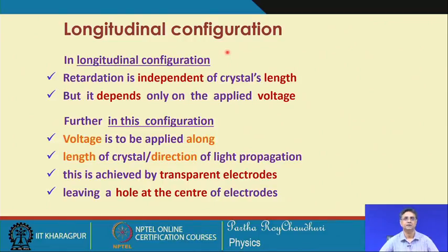As a result, the phase retardation, the phase delay, does not involve the length of the crystal. It is only the voltage that matters; the retardation is proportional to the applied voltage, that is, it depends only on the externally applied voltage.